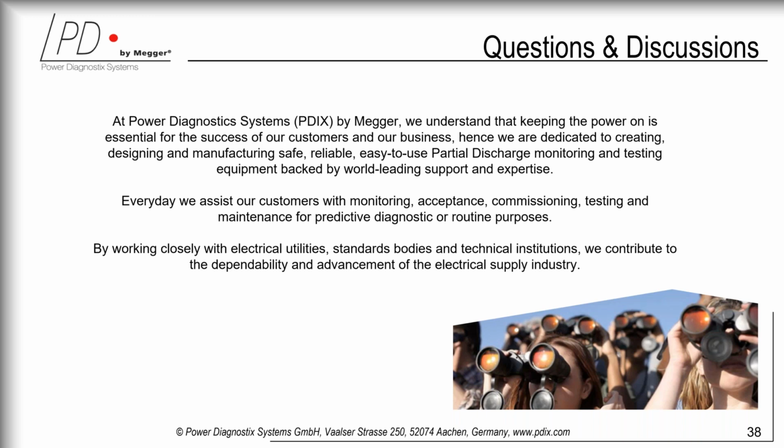It's a very simple analog circuit, but that works for disturbance signals with, let's say, relatively low repetition rate. If we see disturbance signals of very high repetition rate, then we go into a different spectra of the measurement. So the instrument offers different ways to get rid of these external disturbances.